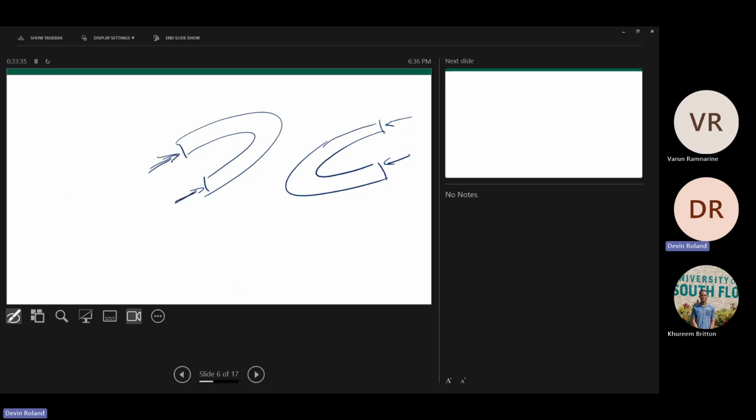But the pressure is always going to act in at your control surfaces. And then the direction of the flow is important, like if it's flowing this way or that way. But where that gets captured is in the m dot U2 minus U1 term. So the negative direction of flow will get captured in that term over there.